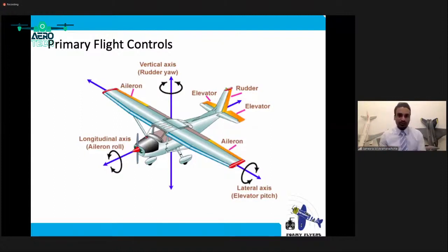To give you an example of how these things work, I have a model aircraft. As I told you before, this is a static model aircraft. I think you might know this aircraft as well. This is an A380. So this is where the rudder is, right? And this whole section of this aircraft is called the empennage, or the vertical stabilizer and horizontal stabilizers. So you have the rudder and you have the elevator and you have the ailerons on the corners of the main wing, right? And how it works, let's talk about the elevator first.